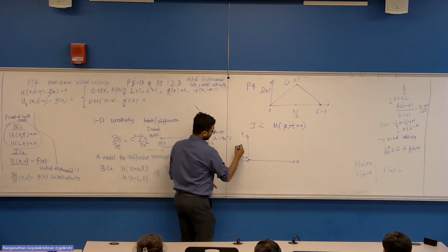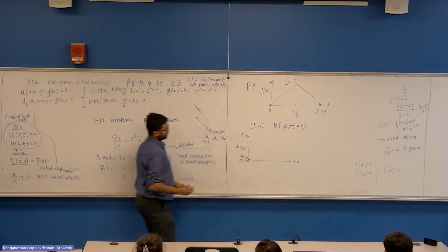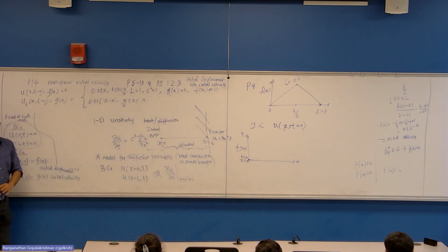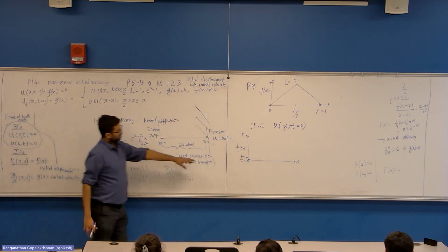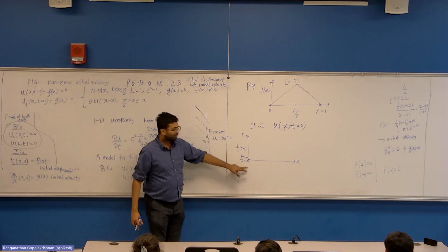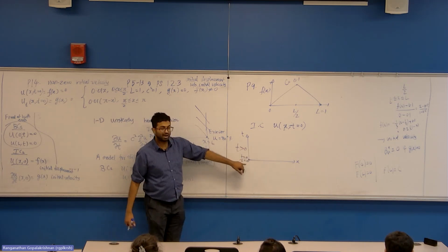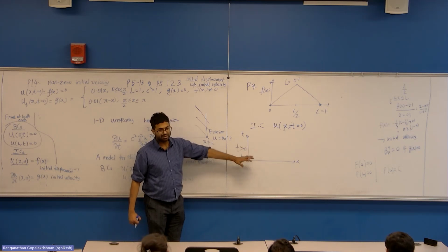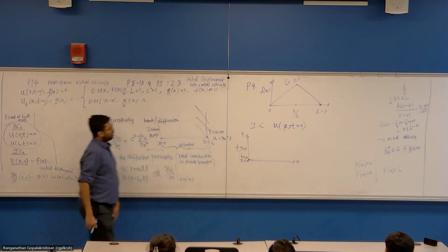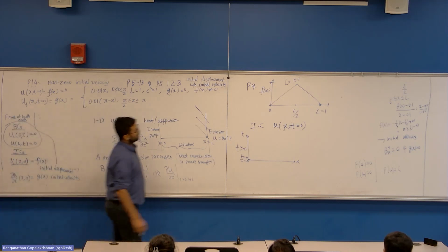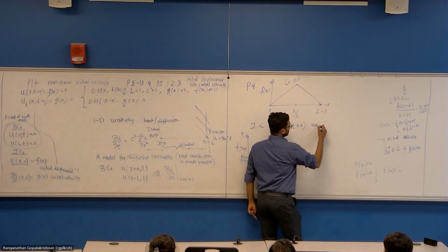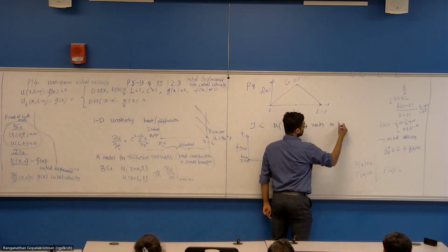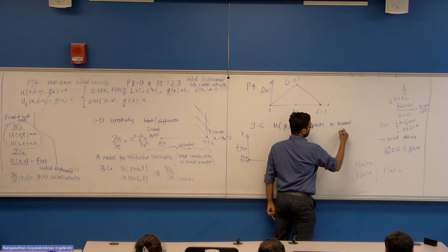So then the problem is defined for positive time. And very soon we'll find the initial temperature profile that you assume at time 0 usually has no bearing on the final solution, especially the steady state solution. You'll see why. Okay. So u of x at t equal to 0 needs to be known or assumed.